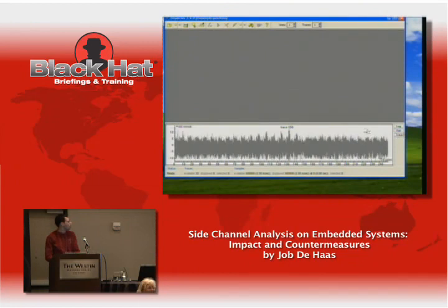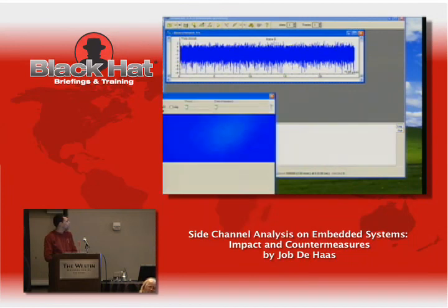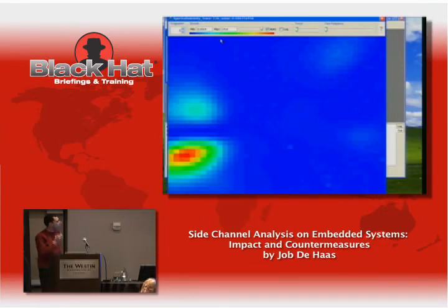I think, wait a minute. Yep. Now, the other thing that we can do with this, and I told you about the XY plot. So here I prepared a plot. I hope still there. Yeah. So what we can do there is we can scan over the surface of the chip, and then for each position you do a measurement like this. So you trigger a DES and you do a measurement, and then you start to look at the spectrum. So you do FFT of it and look at the frequency spectrum.